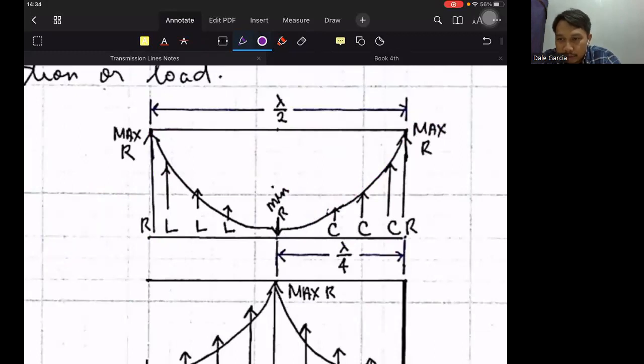It looks like an equivalent circuit, no? As we set earlier, at high frequencies our wire could be a complex circuit, a complex RLC circuit with capacitances, inductances, and resistance and conductance. But if it is specifically 1/2 wavelength long, it's a pure resistive value. Even 1/4 wavelength long is resistive, only a small value.